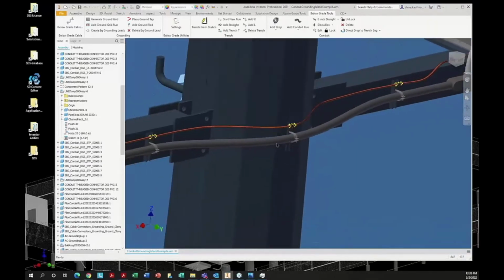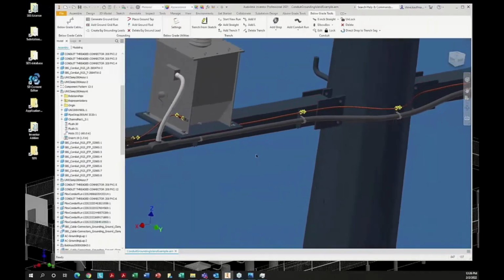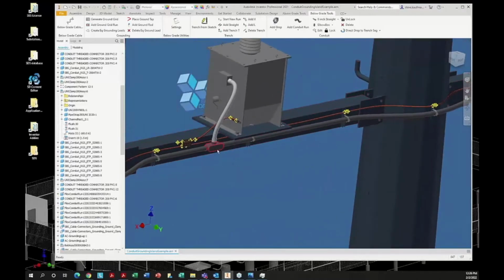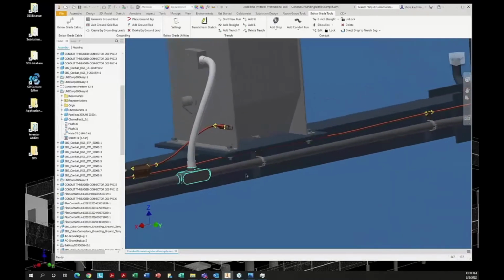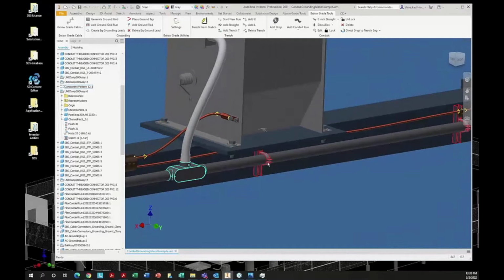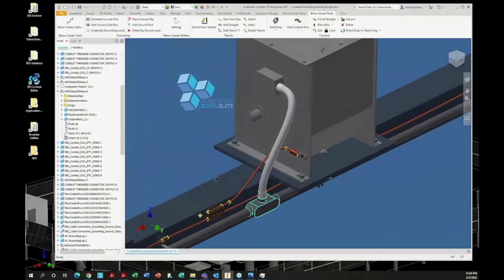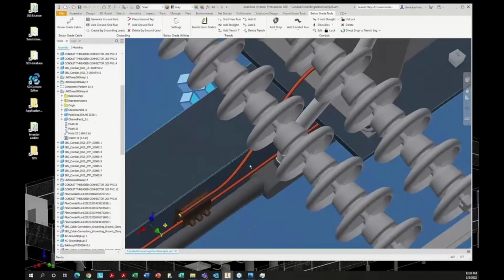Okay, so that's how we're placing these pieces. We're using the fittings. The fittings get placed first. We align our brace or our support pieces with the fitting to make sure we're in line. That fitting, if you look, isn't even touching the side of the steel.